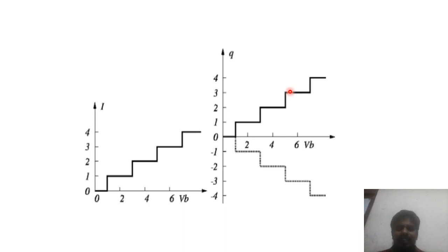What would happen at this low biasing voltage? The Coulomb repulsion between the electrons plays an important role. The Coulomb repulsion is strong enough that it never allows two electrons through the transistor. That means if one electron is flowing through the transistor, then another electron is blocked by the Coulomb repulsion. So it will repel the other electron. It can't flow into the quantum dot because only a single electronic energy level is seen by the electron. So the repulsive force between the electrons will be large. So electrons will be allowed through the quantum dot one at a time. That is the important concept we want to know from this slide.